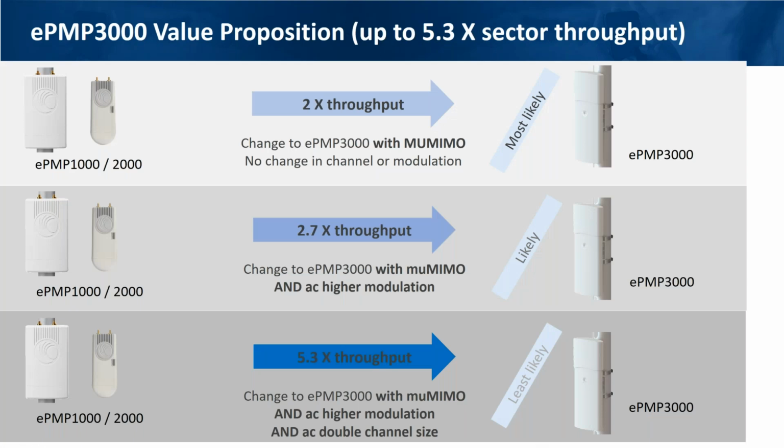Fundamentally, multi-user MIMO means that you're grouping a couple of subscribers and you're able to do MIMO to two subscribers at the same time. It doesn't really depend on channel conditions and interference levels, because whatever you're getting today, if you're able to somehow meet the grouping requirements, pretty quickly you should be able to push traffic to two subscribers at the same time, so potentially doubling the performance that you see today. If you were lucky enough to get up-close subscribers, and your interference levels were low, and we're starting to see this, in some cases you will end up getting that higher modulation benefit too.